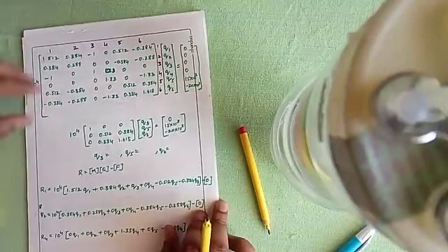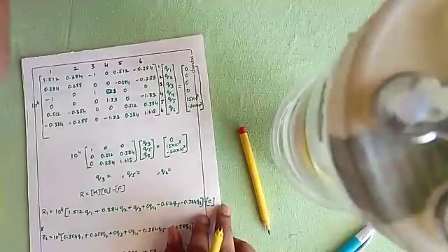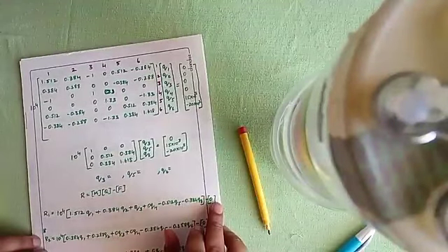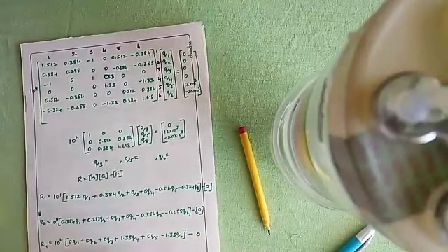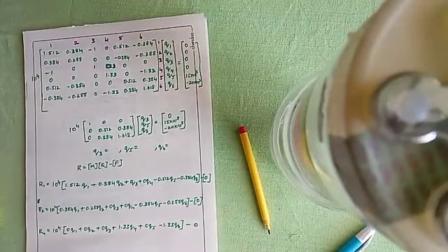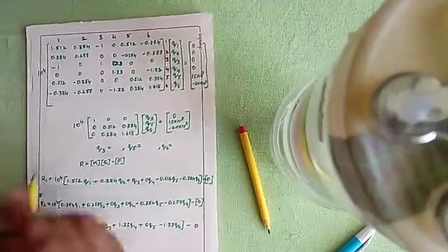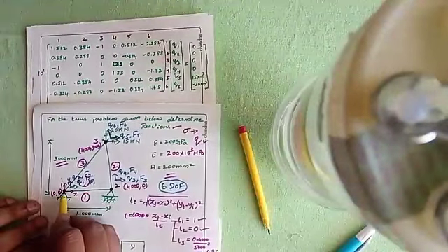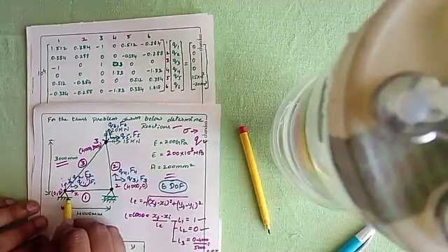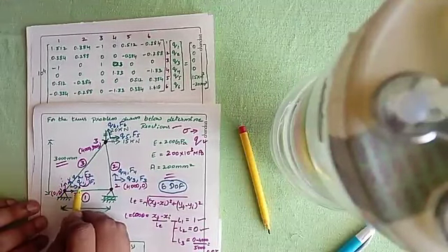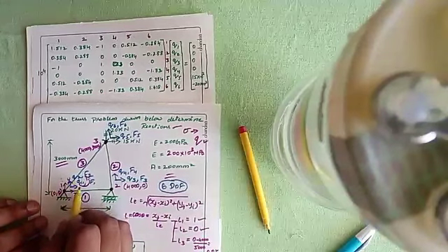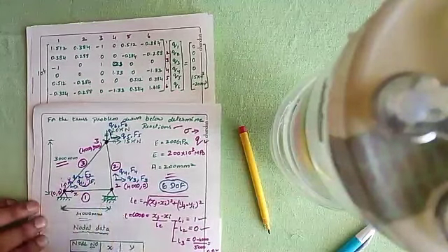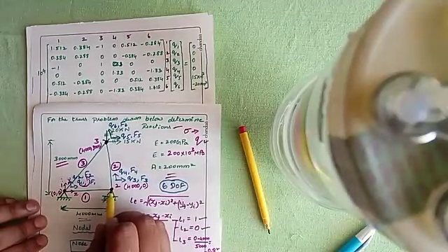Now we need to apply the boundary conditions. We are going to apply the boundary conditions by the elimination method. Again, utilize the diagram carefully. See here, you can see node number 1 is completely fixed. So that means when it is completely fixed, there will be no displacements along x and y direction. So Q1 and Q2 will be equal to 0. Now let us come to node number 2.